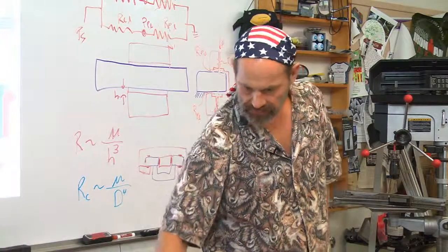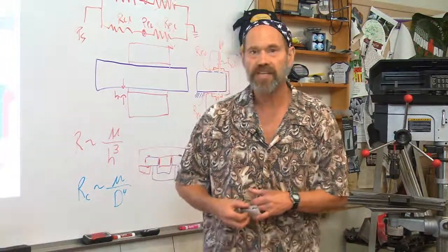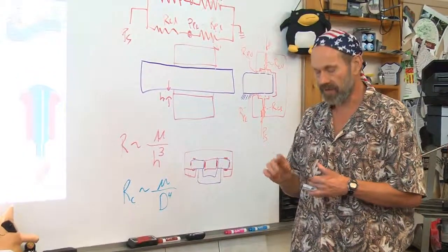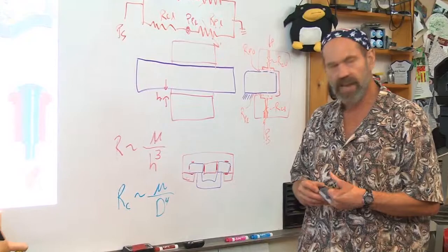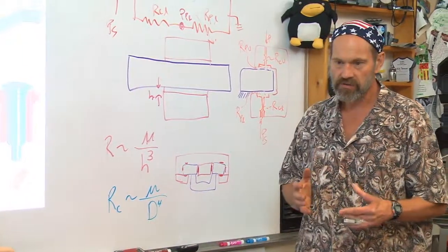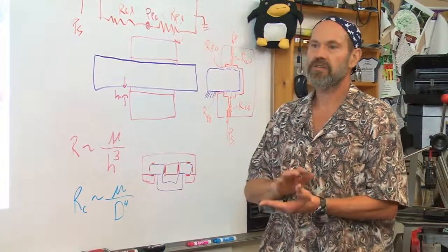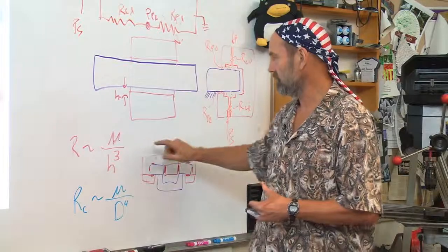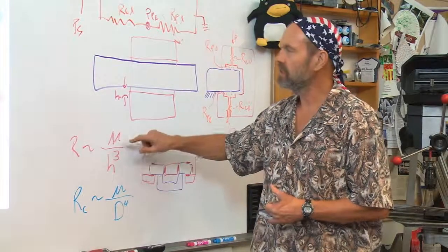Now, the other type of hydrostatic bearing, or aerostatic bearing, uses air instead of a liquid. For a liquid, you may use oil, and oil is very nice. The resistance that you need in your system is easy to achieve because of the high viscosity of oil.